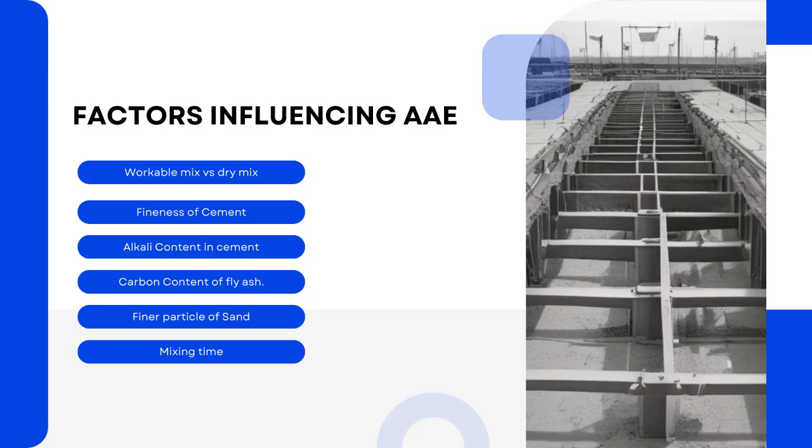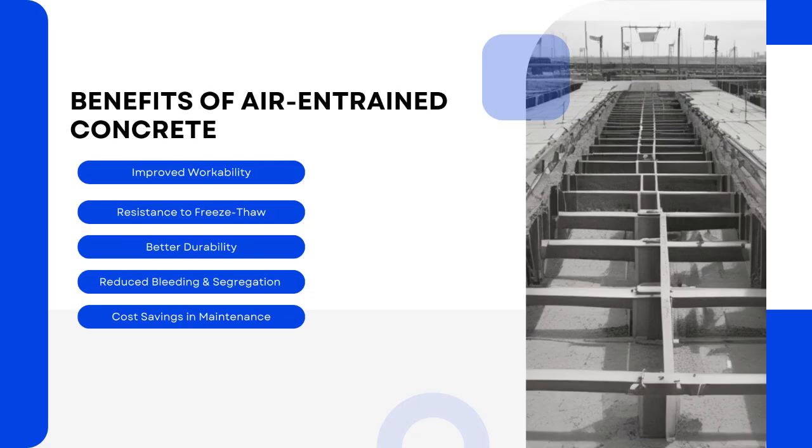So what are the benefits of air entrained concrete? As we all know, improved workability. The tiny bubbles act like ball bearings, making concrete easier to place and finish. And resistance to freeze-thaw cycles, which I already discussed. Better durability: the service life of concrete structures increases significantly, and it reduces bleeding and segregation. These are the importance of air entrained concrete.